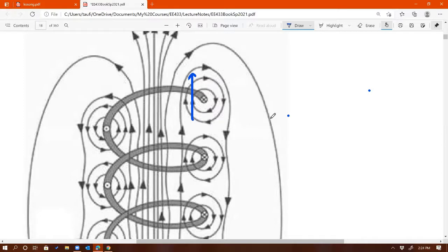Agree? Okay, so now remember this wire is going around a core. It could be air, like this picture, but it could be any core. So imagine this wire is wrapped around a core. So now it goes to this side right here, the other side. This is one side, the right-hand side of the core. Here's the left-hand side of the core. So that same wire, same current. Now look at the current. Since this is a coil, if the current is entering the page here, on the other side the current must be leaving the page, yes? You agree with that, yes?